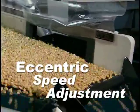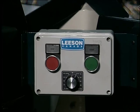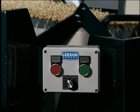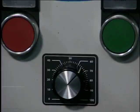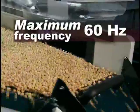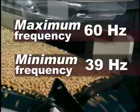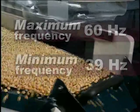An electronic variable frequency motor controller is used to adjust the speed of the deck's side-to-side eccentric motion. Turning the control knob clockwise will increase the speed, and counterclockwise will decrease the speed. The maximum recommended frequency is 60 Hz and the minimum is 39 Hz. These limits should never be exceeded.